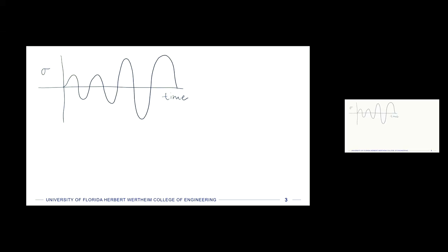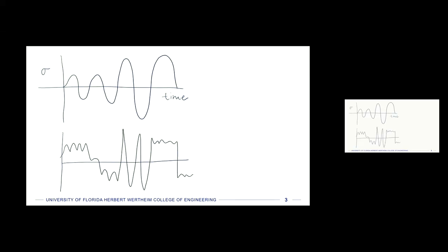We could also have different phases of this curve, same axes, stress and time, that have different mean stresses. So we could have some cyclic stresses like this, then back, then up and down. This is what would happen maybe in machinery that has different loads over different times that's not determined by predictable mechanics.